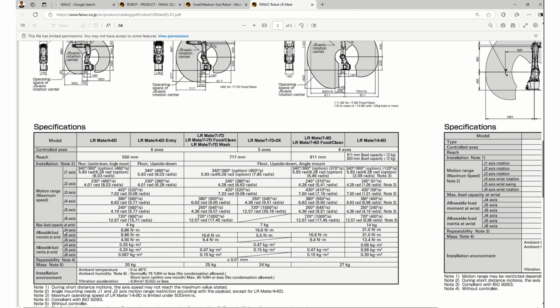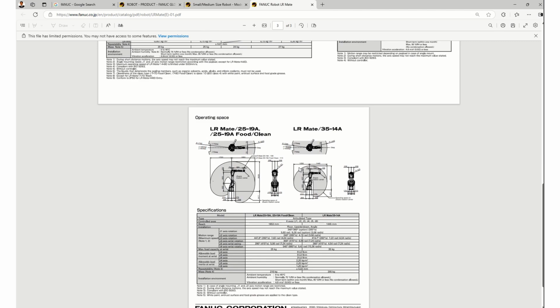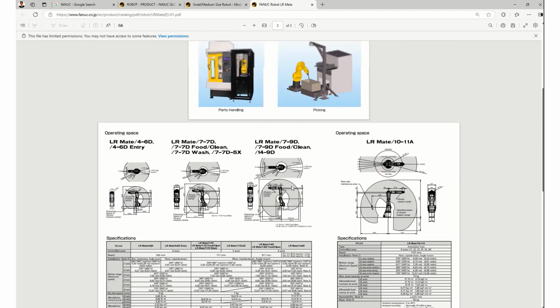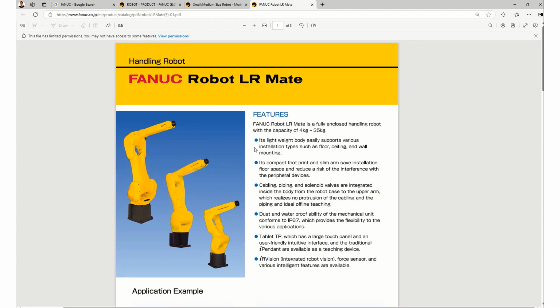Now these things are important while designing the end of arm tooling, because they will have some moments, and we need to check whether the wrist joint can take up those loads or not. And these are the inertia loads, as the robot moves at high speed, so we need to take into consideration the inertia loads also. So that's how we need to check the moments on this wrist, these axis, like you can see the J4, J5, J6, and basically the J6 can be a wrist, so we need to check for the moments. So this is about the articulated or joint arm configuration of the robot.